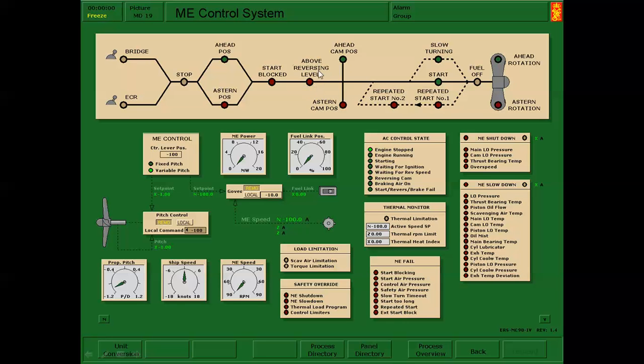If you're moving above 6 knots, you'll not be able to go astern. The reason is you have a large propeller at the back of the vessel with water moving across it at 6 knots, which tends to keep the prop turning, and the main engine will be revolving.